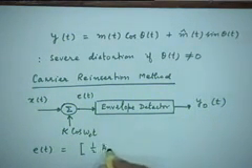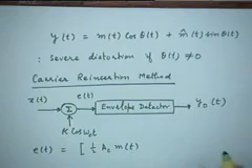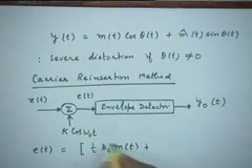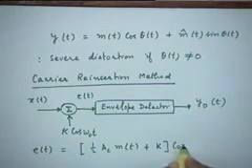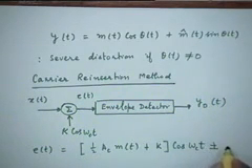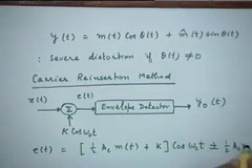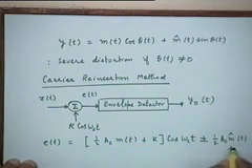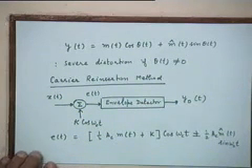The in-phase part of the SSB signal was half Ac m(t), right? This was multiplying cosine omega ct, plus you have a constant amplitude carrier k here, and these two together now constitute the so-called in-phase part of the SSB signal. And what is the quadrature phase part? Well, depending on whether it is lower sideband or upper sideband, we'll have half Ac m hat (t) into sine omega ct. Okay.